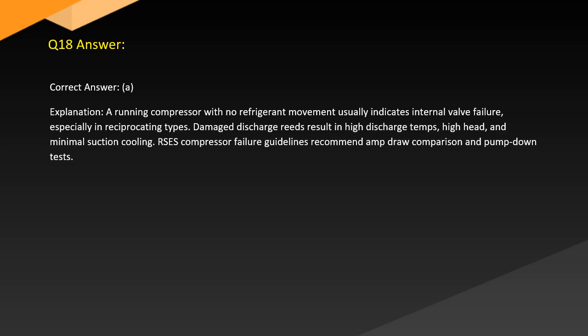Answer. Correct answer, A. Explanation. A running compressor with no refrigerant movement usually indicates internal valve failure, especially in reciprocating types. Damaged discharge reeds result in high discharge temps, high head, and minimal suction cooling. RSES compressor failure guidelines recommend amp draw comparison and pump down tests.